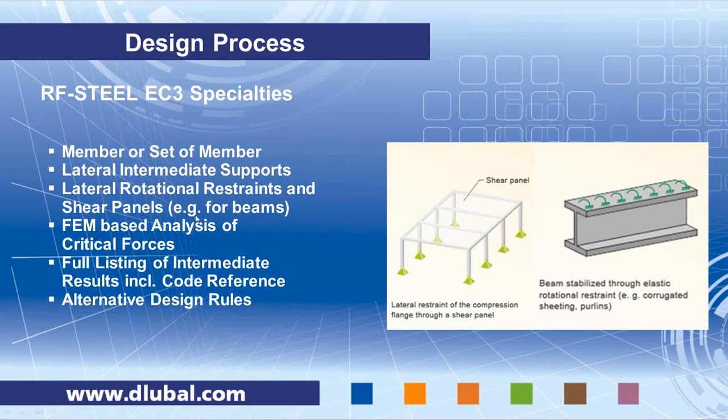Also, it is important that you have a good, stable numerical solution for your critical forces, namely the critical axial force and the critical bending moment. In the code, there are simple analytical formulas, or mainly in the national annexes, with parameters C1, C2, C3. Those are derived from a simple fork-supported one-bay beam.